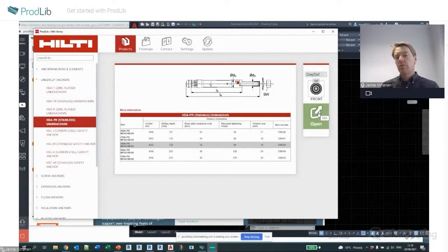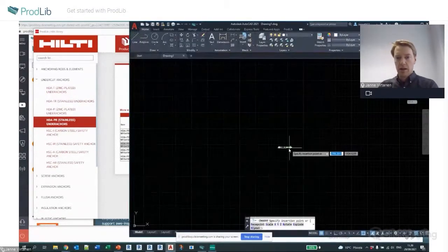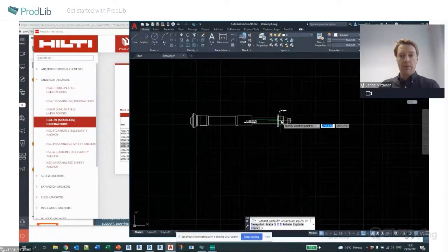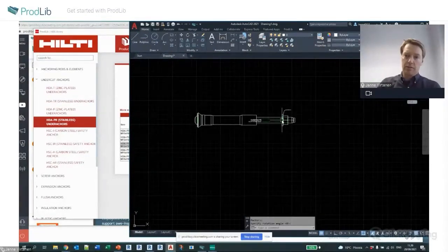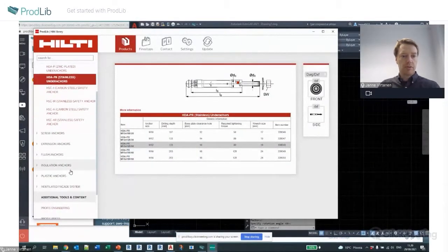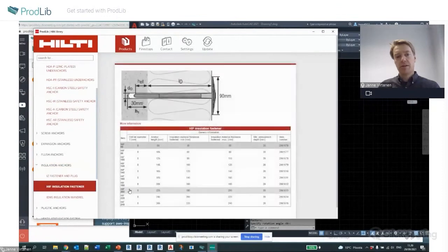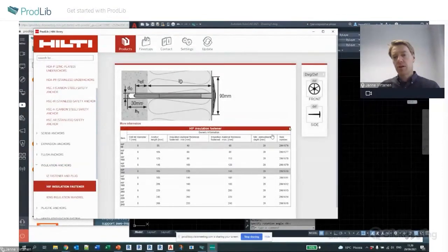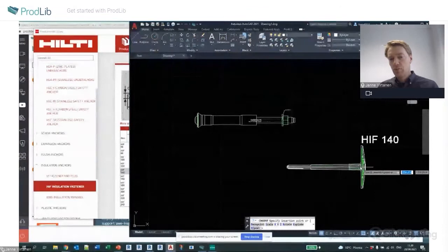So if I click now, it will open a default CAD viewer. If it's AutoCAD, BricsCAD, whatever it is you have set in Windows as a default CAD software, it will open it there. Or I can drag and drop it, so I can just drag it to the open CAD software that I have. The insertion point and the scaling, what it asks for X and Y direction. So try to find what you need, have the product version, and drag it to the open drawing.